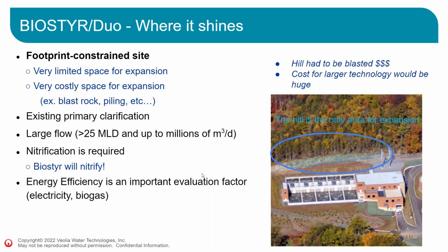It's also a good project when there's some nitrification required, because the Biostyr can do BOD and nitrification removal in one single cell. So there's only one step needed. You don't need two steps to do both. And it's an energy efficient technology. I will talk a little bit more about this one later on.